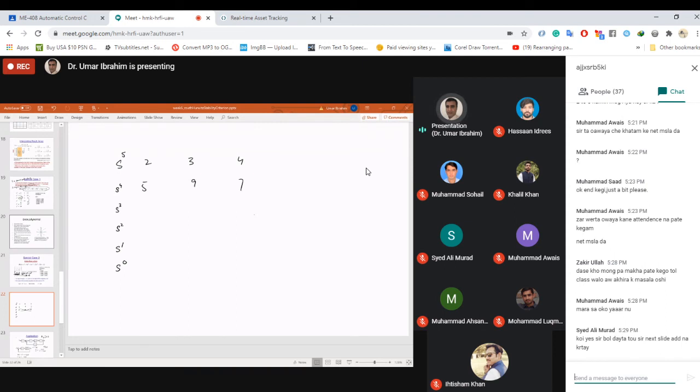Okay? What you will have to do is that rather than writing 0, 0, you will take the upper polynomial. You can convert the upper row into a polynomial. The 5 is a coefficient of S4, we know that. 9 is a coefficient of the next even power, S square. And 7 is a coefficient of the next even power, which is s raised to the power 0.